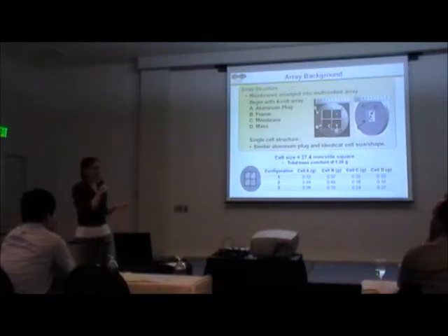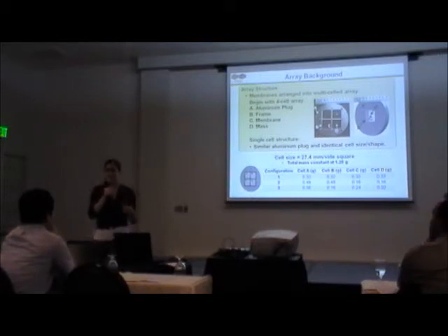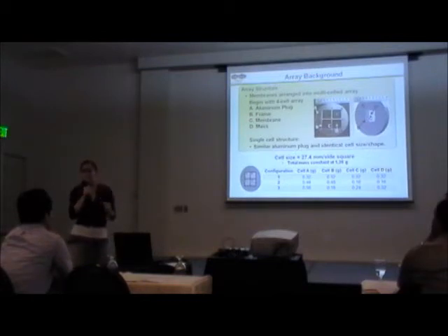We started, for experimental purposes, with a 4-cell structure. So a single membrane was stretched over a frame that divided the membrane into 4 different cells, and then that was mounted on an adapter plug so that we were able to use the same round impedance tube that we used before, and masses were attached to the center of each of the membranes.